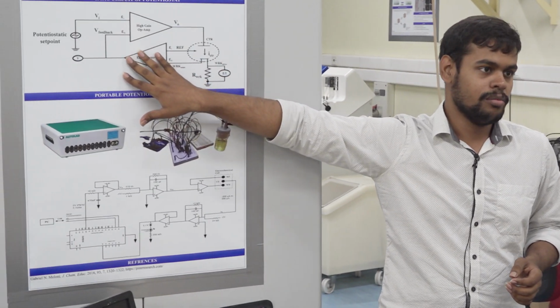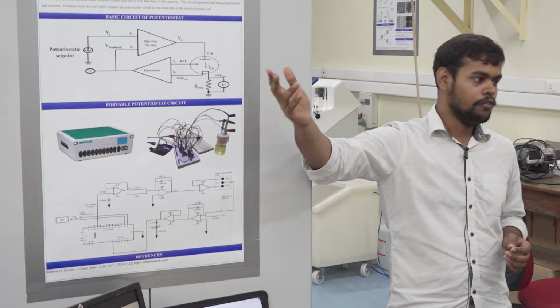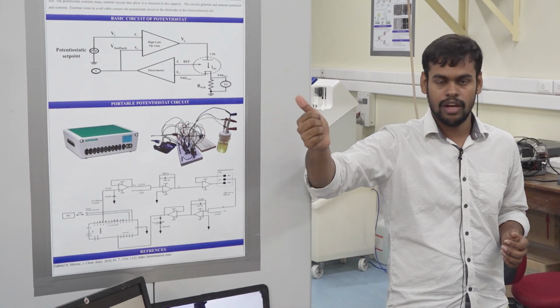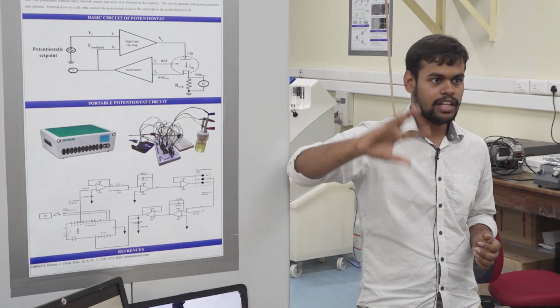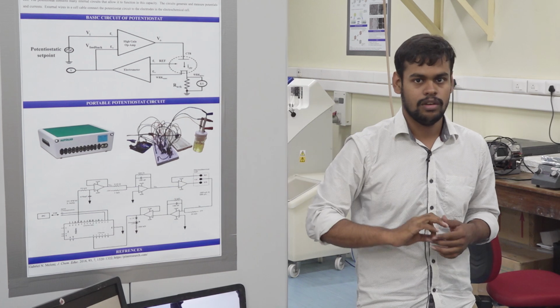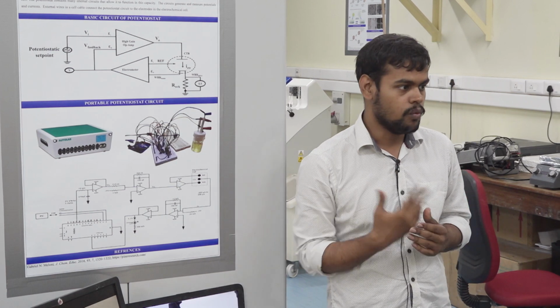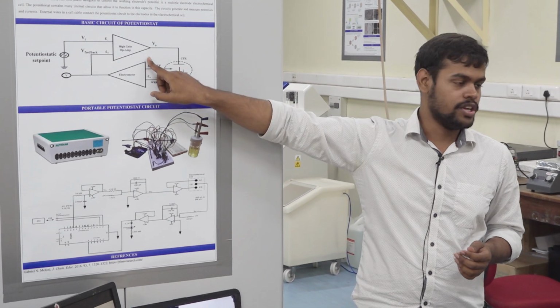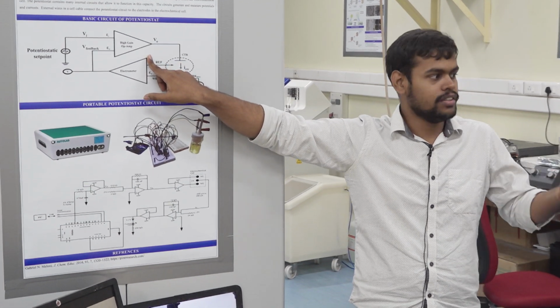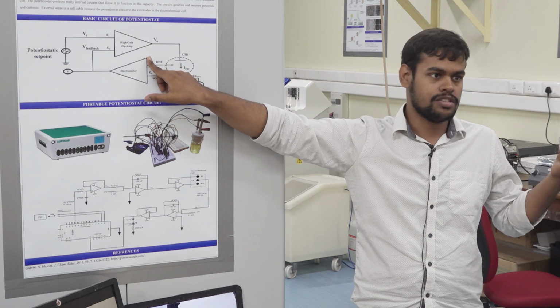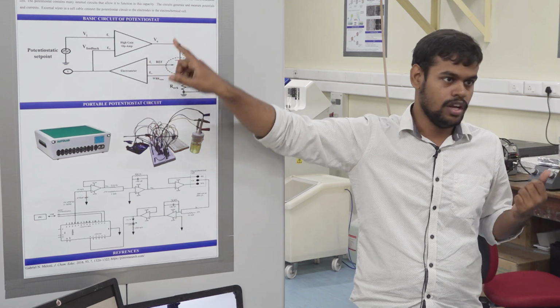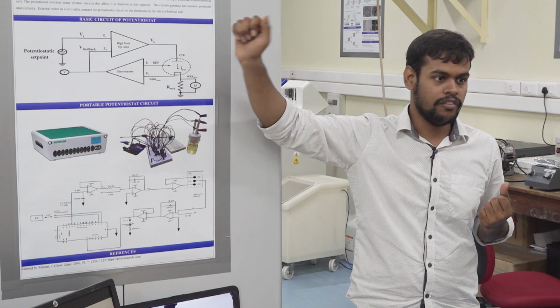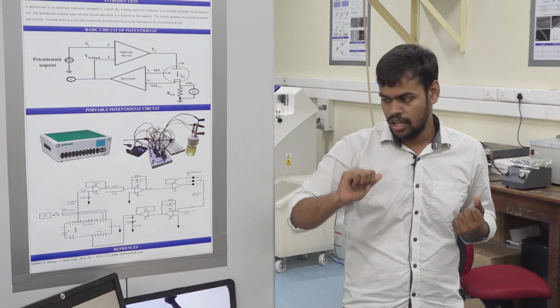When we do an electrochemical study, corrosion happens, and we simulate it in our lab. We simulate on a potentiostat, and we then tell that this material can work for this much time. How does that happen, what goes inside that? What goes inside is the operational amplifier connected with the ADC and DAC, analog to digital converter and digital to analog converter. Here I am showing you the main circuit where potential to current or current to potential conversion happens.